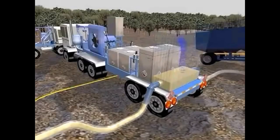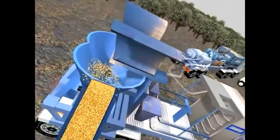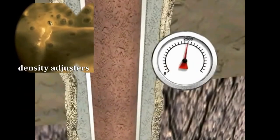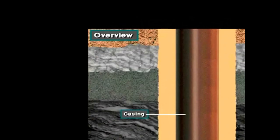First, dry cement is mixed with additives made up of accelerators, retarders, and density adjusters. The function of these additives is to adjust the dry cement properties to fit the conditions of the well. Accelerators speed up the setting time of the cement. Retarders do the opposite. They prevent premature setting in deep, high-temperature wells. Density adjusters increase the cement weight to reduce pumping pressures or to permit a higher cement column without fracturing the formation.